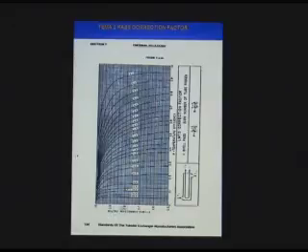Ideally, you're 80% or greater on the correction factor. As you get down to 70%, the ability of the exchanger to perform correctly is questionable. So anywhere from 80 to 100% is basically the desired correction factor for a stream.